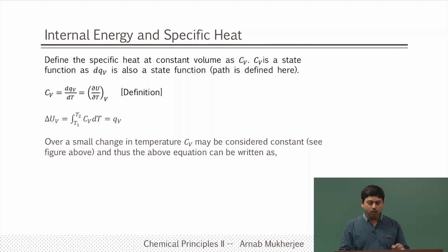Now, when I do this particular integration, the Cv may or may not be dependent on temperature, right. Because it is inside the integration, this particular Cv may or may not be dependent on the temperature. But it turns out that for a region of our interest, when you are changing the temperature from T1 to T2, in that region Cv may not vary much with the temperature, and in that case we can always take the Cv outside the integration and we will get the change in the internal energy as Cv (T2 minus T1).